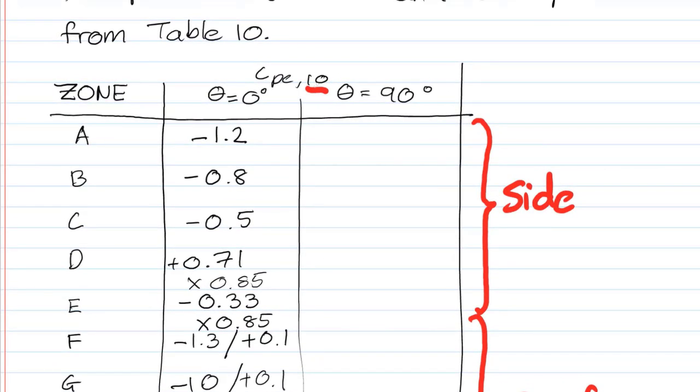And now, just to remind you of what we've discussed previously, we are working with CPE 10. In general, what we are looking at is bigger than 10 square meters. Purlins, roof trusses, columns, most of them are carrying more than 10 square meters of loaded area, therefore CPE 10 is what we are using. If we were designing something very small, 6 square meters of tributary area, 1 square meter of tributary area, we would use a CPE 1 or a CPE 6.